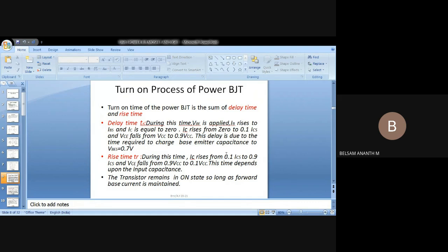During both stages of your system, you have to consider time parameters. Whenever we speak about frequency response, we also should focus on the time response. That means delay time, rise time, peak time, settling time, overshoot. These parameters deserve considerable concentration when you go for a complete process. So when you want to analyze a complete frequency response or a time-related analysis, please remember to keep these time parameters in mind.